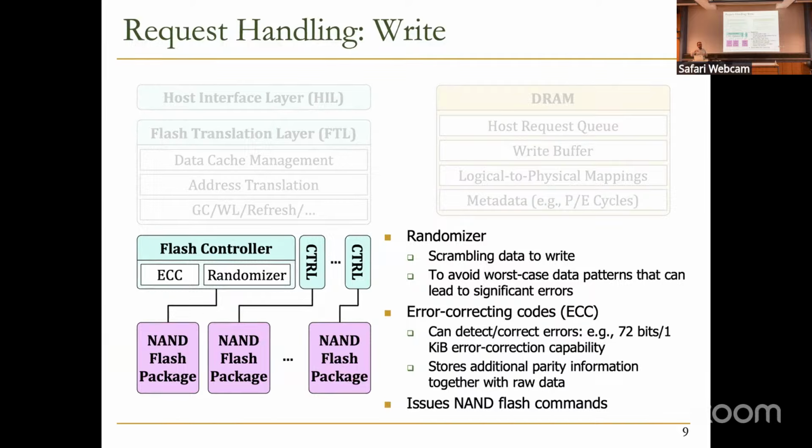Remember that when we wanted to profile retention failures, we had to do that. We discussed it, right? So if people know about worst case patterns, they can potentially use those, maliciously or not, and that would cause the worst case errors, which in the end ECC is not strong enough to support. We want to avoid those cases, which put a lot of pressure on ECC and other reliability techniques that we have in the system. So by randomizing, you're reducing the likelihood of those cases, essentially.